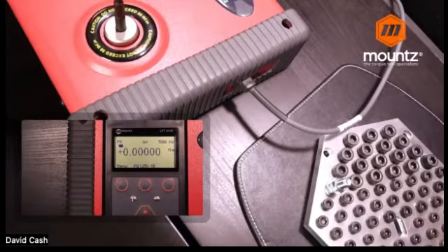If you're doing a number of different tools and different tests, you just want to make sure that all of the values that you are reading are still within the spec. Again, the tool test type function gives us the ability to capture tool data with a time and date stamp. Then we can pull up that information and evaluate it over a period of time to make good decisions about when we calibrate or how we calibrate those tools.